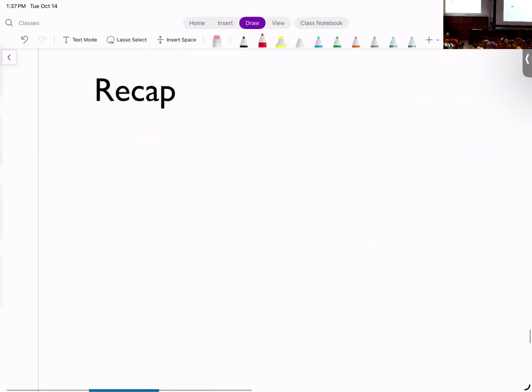Good. All right. So to just recap, I introduced multiple concepts. First, I introduced the notion of pipelining and showed you why pipelining helps us increase performance. I showed you the changes required in our data path and controller to support pipelining. Essentially, each instruction is a block of data and controller, and you pass this along to the next cycle, okay? Then we saw 2 problems. Problem number 1 was data hazards, when there was dependency between the source and destination of the instructions. How do we fix that?